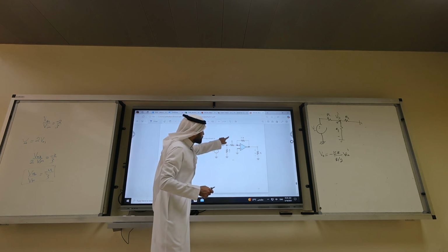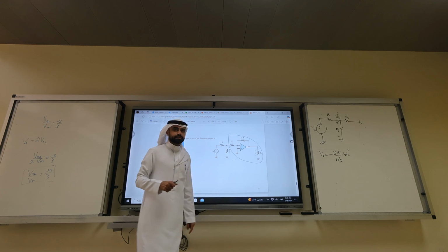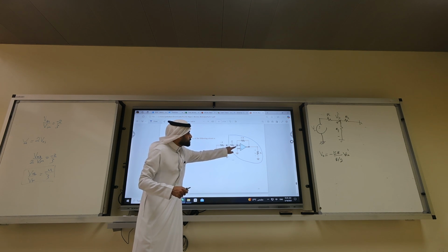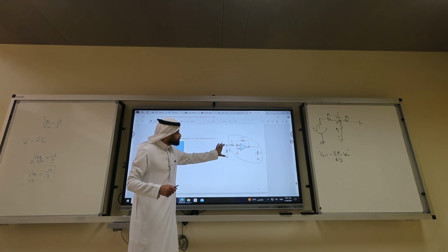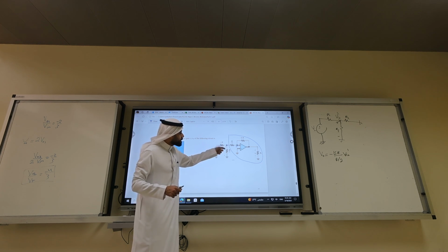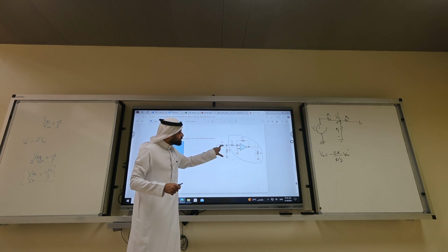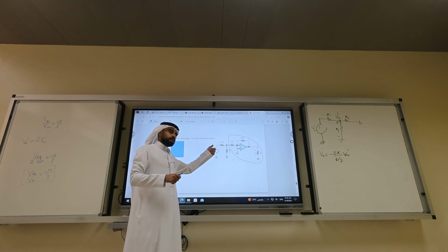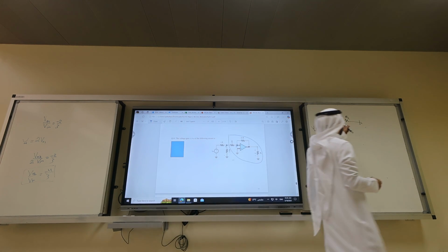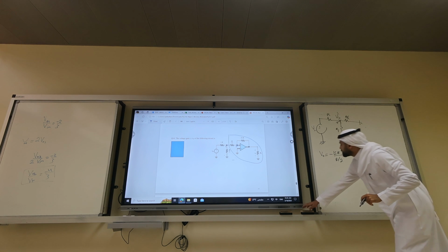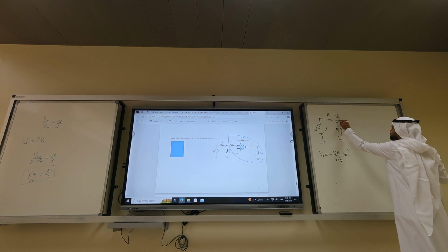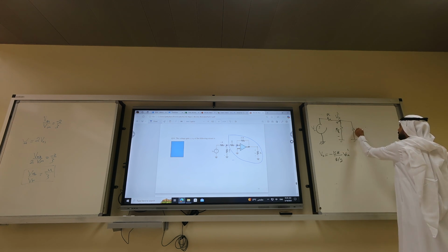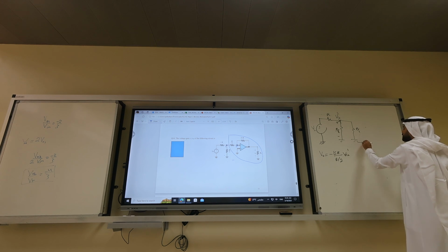You know that you have here a non-inverting amplifier, right? Here I have another system. Because of the virtual ground, I need to know this voltage. This voltage is not the VDR between this R over 2 and 1R. It's actually the VDR between the parallel combination of this R over 2 and this R over 2, in series with 1R. So can I redraw the circuit to be like this? R over 2, R over 2. This is the virtual ground. Can I do it this way?